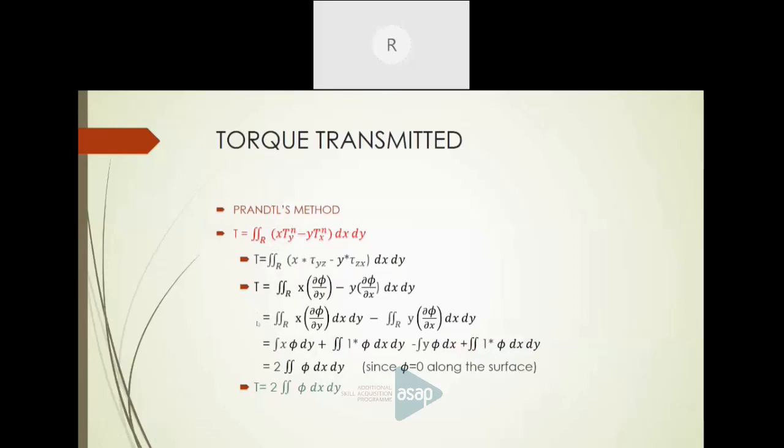So what is the St-Venant method? St-Venant put his entire consideration on the warping. We have already seen that warping is the W displacement and it is a function of x and y. So he introduced a function known as the warping function psi. How are psi and W connected? W is equal to alpha, the angular twist, into the function psi. So he related the warping displacement W to the function, that is W is equal to alpha into psi of x, y. You know warping is entirely dependent upon x and y, so the function is psi, some function in x and y.